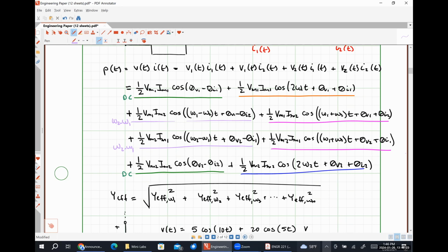One of the advantages of a split phase system is that if we were to accidentally stick a knife or a fork into our outlets, we will get shocked less than we would if we did the exact same thing in Europe, because the magnitude of the voltages is always going to be smaller. So in the US, it is arguably a little bit safer because we use 120 for practically everything as opposed to 230 for literally everything. Yeah, so anyway, that's just a rant about things.